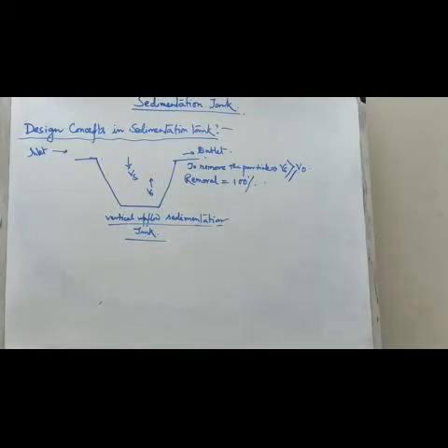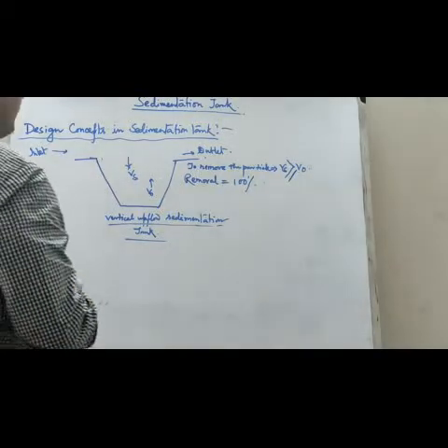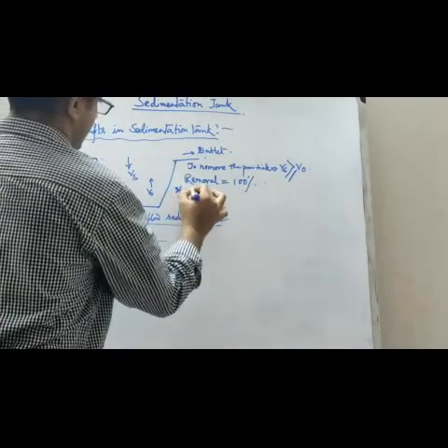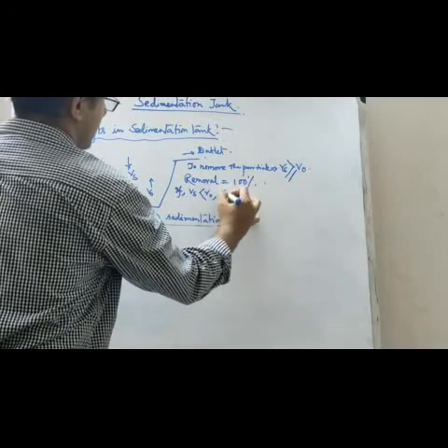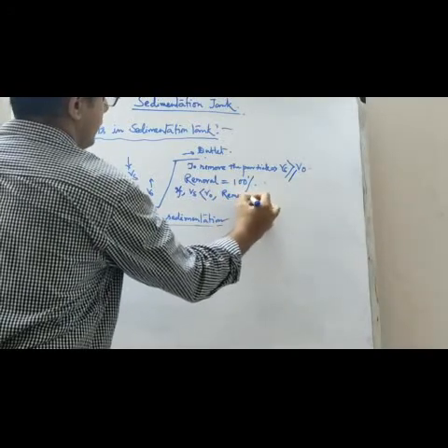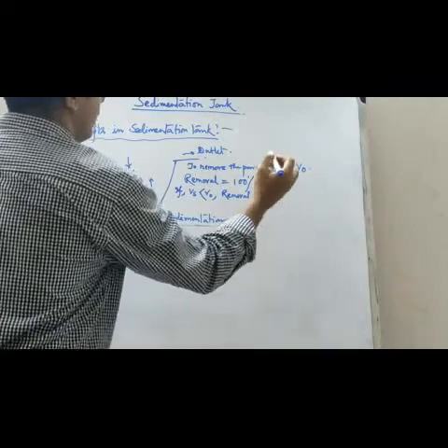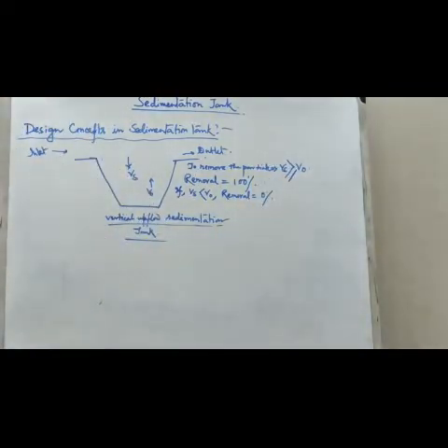One would expect 0% removal. If Vs is less than V0, the removal is 0%, because no suspended particles should reach the outlet, as Vs is less than V0.